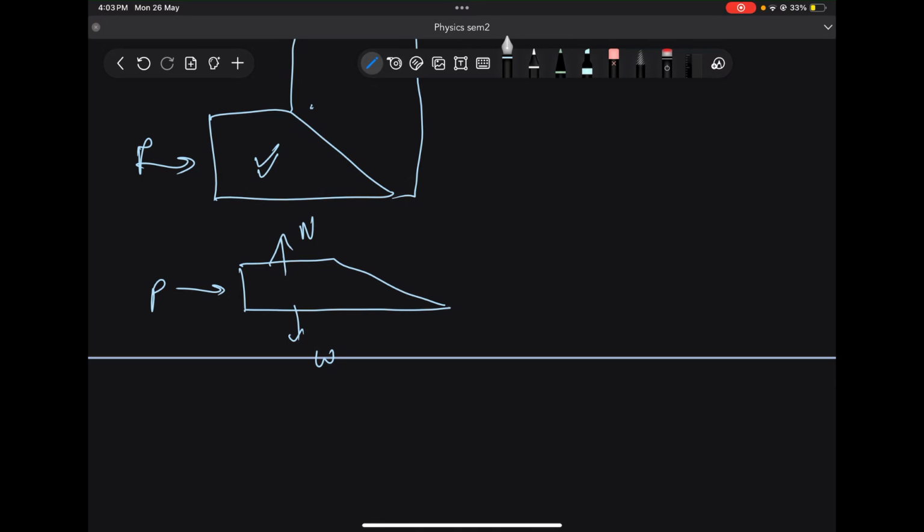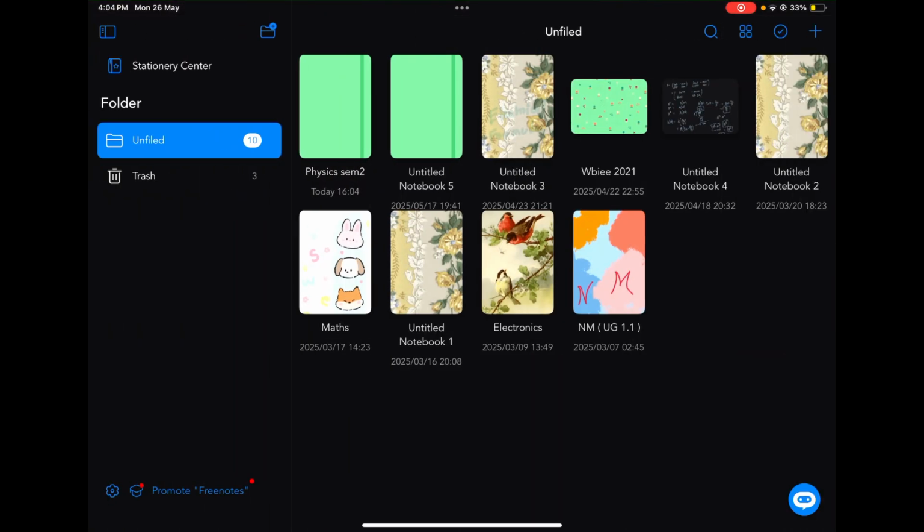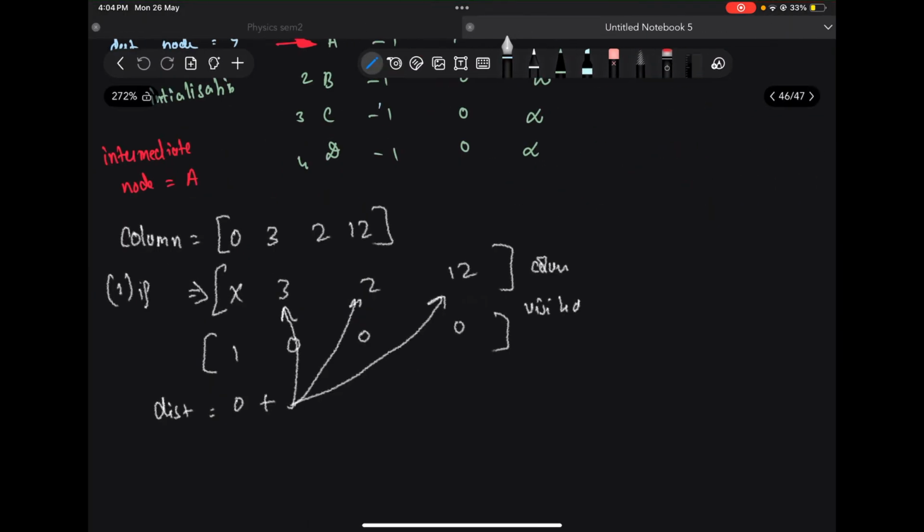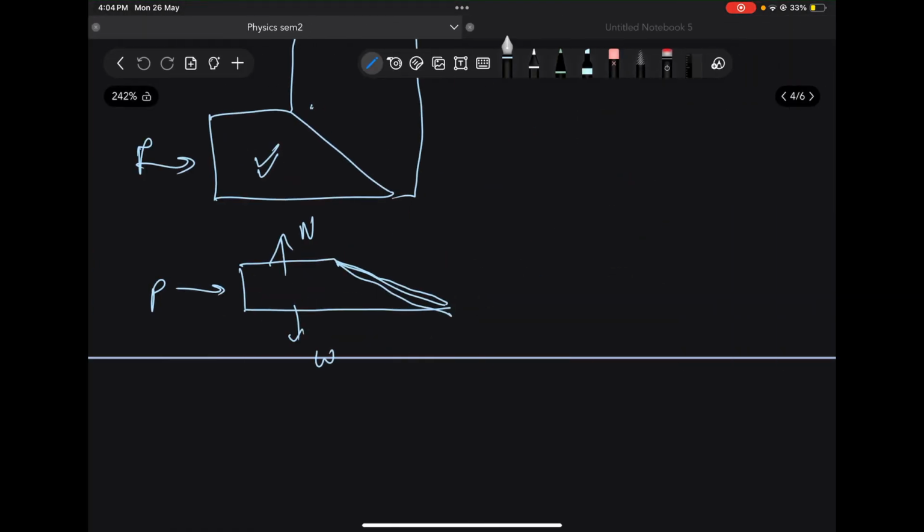Now the normal reaction will always apply perpendicular to this face surface. So you can take NB, let's say, over here. And since this block is prevented from sliding down in this direction, the friction force will be like this, some force F. And with that, you can calculate the net force.